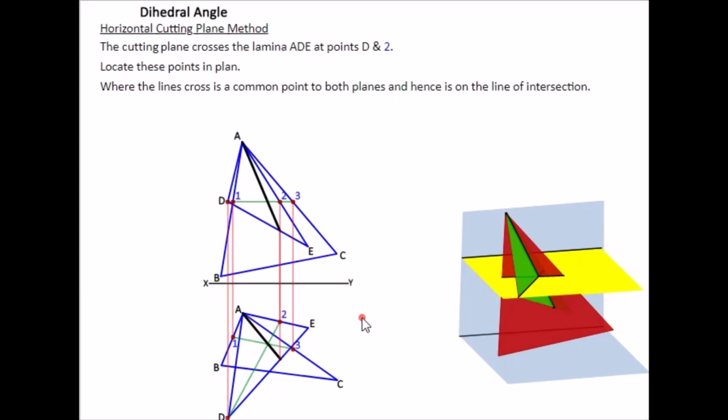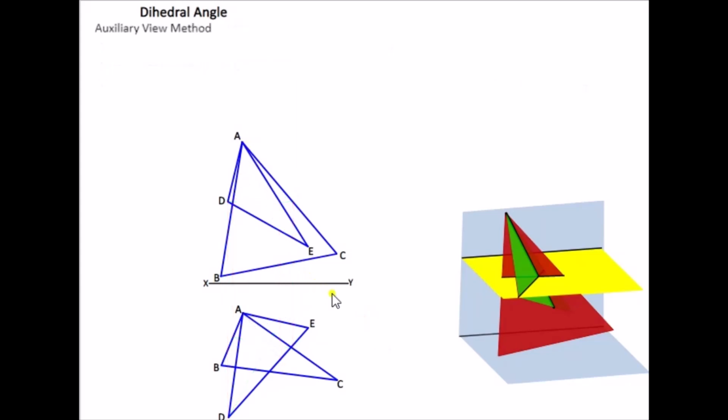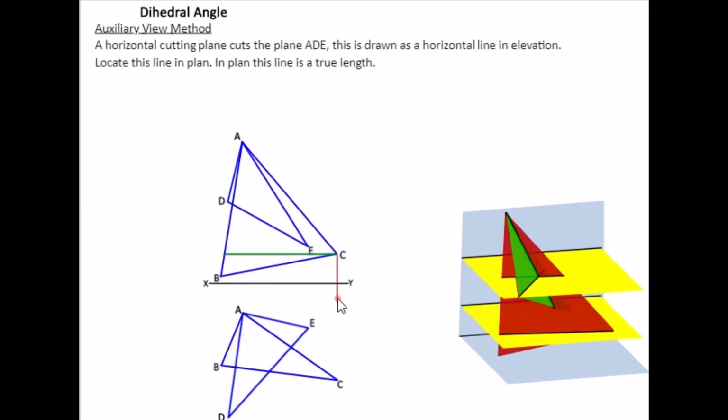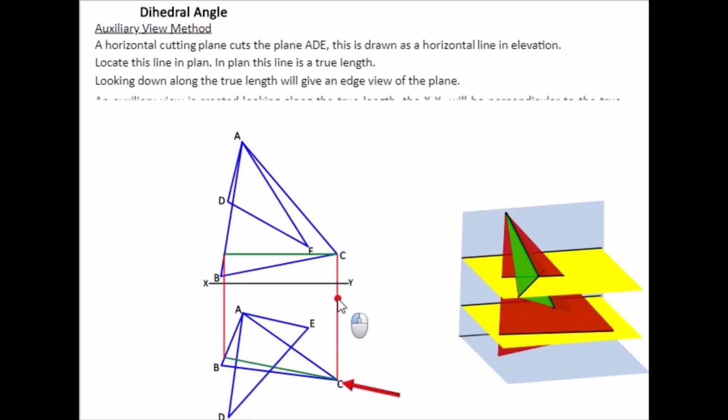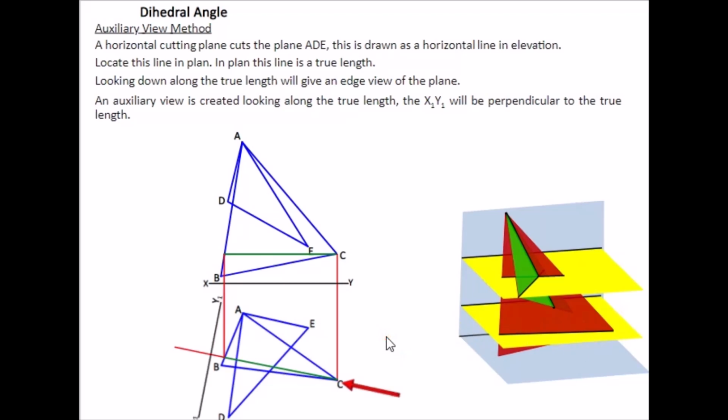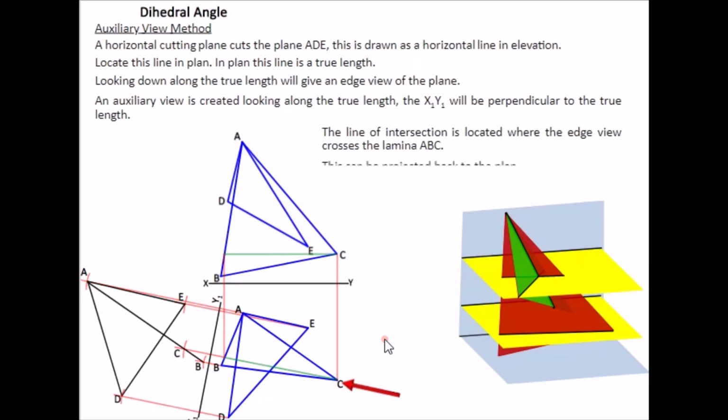And next then, now we'll skip through this here again. If you take a slice, in this case here, we're taking a slice down lower, and what we'll notice here is only cutting through one triangle. So what we're doing here is we're doing the auxiliary method here. So I'd recommend stay away from the auxiliary method because it's extra drawing that you'll have an extra auxiliary on your page and you mightn't have room for it.